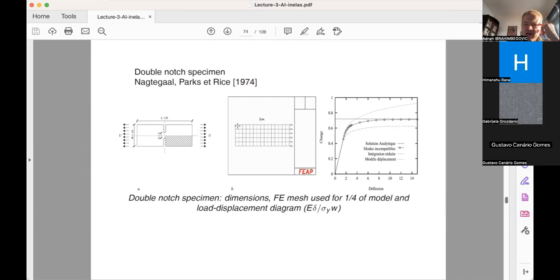This is really the case that I was discussing, because here you have a support, here you have a support. So due to the incompressibility, you can see up here, plastic deformation is much larger than the elastic deformation, because if you unload and you follow this straight line, your elastic deformation is a fraction of the plastic deformation. So your behavior is not incompressible, which would lock this completely, but it's so-called quasi-incompressible. The change of volume should be close to zero. It's not zero, but very close to zero, or an order of magnitude smaller than the change of shape. And unless your finite element interpolation has this ability, there's no way you can represent that.